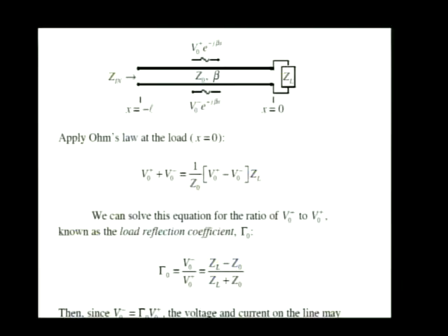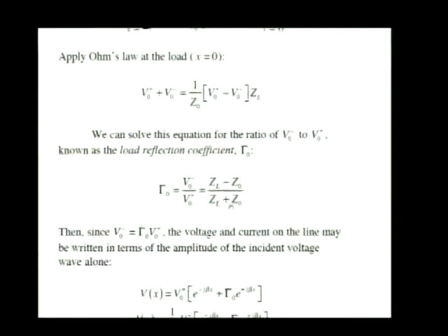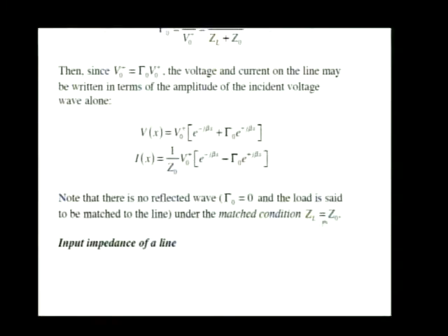Efficiency is one reason. Other reasons might be that having 5 watts traveling from the source down to the load and having 1 watt being reflected back up the line into the output terminals of the source could damage the source, maybe even burn it out. So for a lot of reasons, we often shoot for a matched condition for our loads.